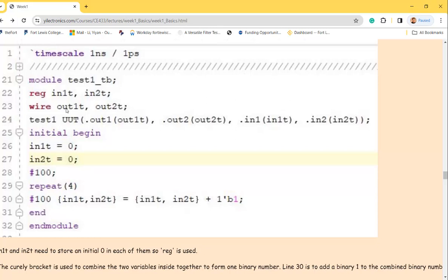If you look at the code, I think I talked about this very briefly in the morning. Why do we want to make the inputs a register type instead of wire? But output doesn't matter because it's just a metal, right? I just need to probe it. Just a wire, just a piece of wire. But the input needs to be a register type. Why is that?